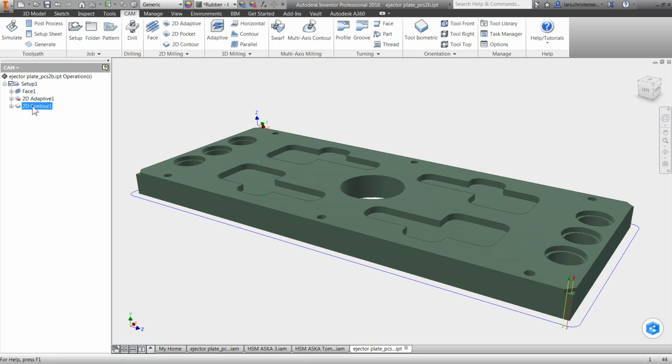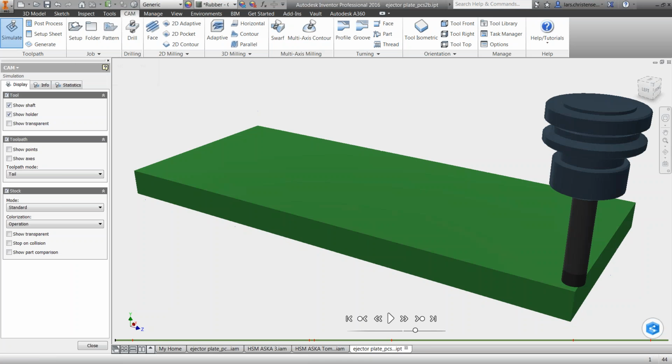So it's actually giving us a warning saying, hang on, this toolpath might not be up to date. But what I want to show you is that if I go in now and hit simulate, you will see down at the bottom of our simulation, we hope this shows, we have a couple of red areas here. This is because the software noticed that since we only have very little flute length, we are going to have an issue machining all around this part.